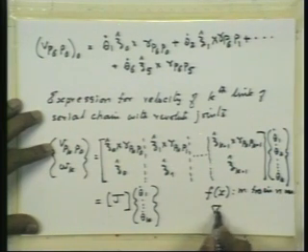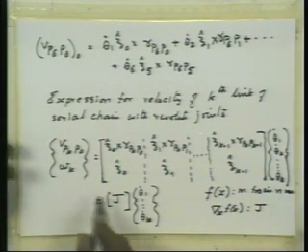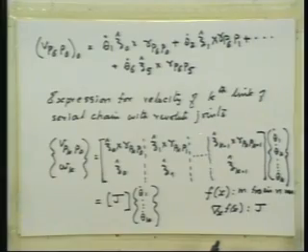So the first order partial derivative of f is called the Jacobian. There is nothing but that. If you have the position of the kth link as functions of these thetas, position is represented by 6 parameters, right? And they are functions of the thetas. So that is why this is called the Jacobian.